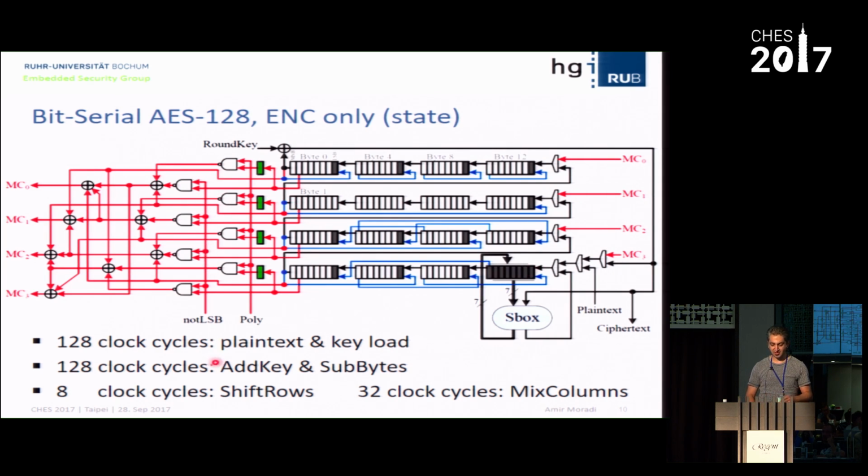Another control signal is required, the last bit for multiply by 2: when you shift everything to the left for the multiply by 2, the LSB is always 0, right? This control signal plays that role.